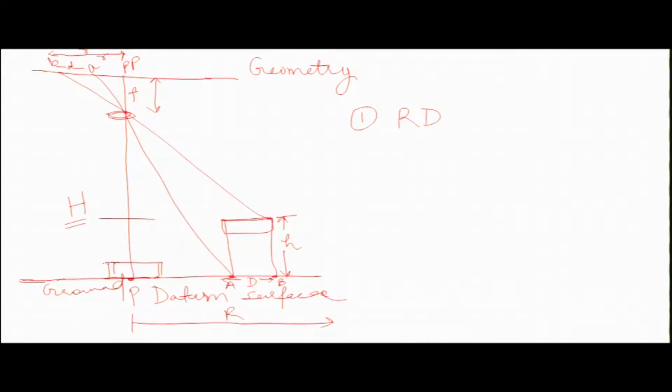So this will be represented in a true shape. The top of this building, suppose this is of rectangular shape, so from whatever height you will see it, this will be shown as the same shape, okay, that is rectangular. So what it means, the objects or the buildings which are located at nadir point or directly below the perspective center will have no relief displacement, okay, will not be affected by the relief displacement.